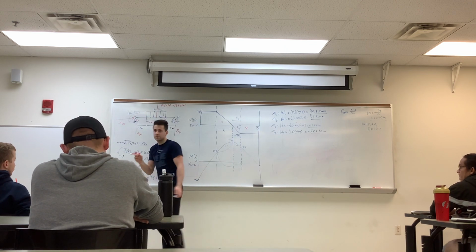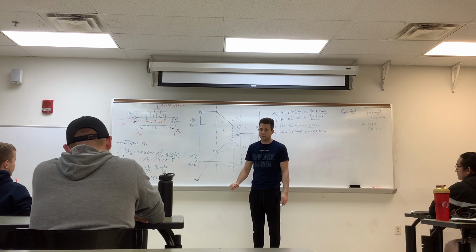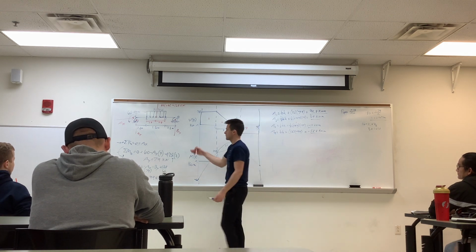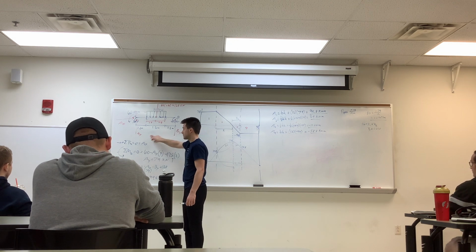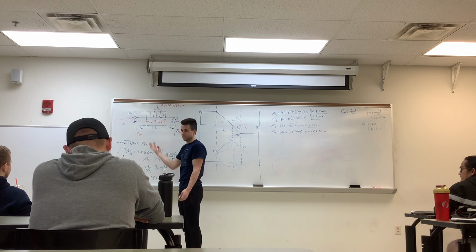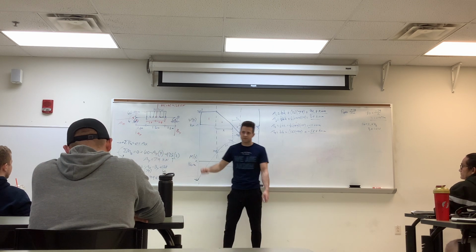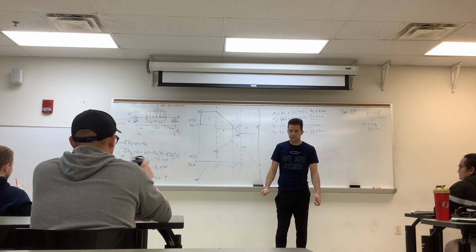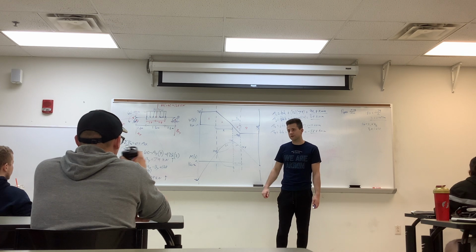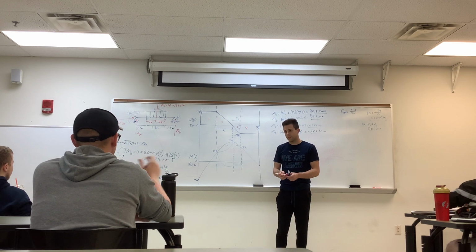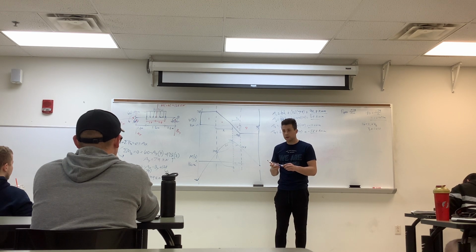Yeah. And the shear, you don't start with anything, right? No, it'll always be 0. So the first step would be always find your reactions. And then that's where your shear diagram will start, the reaction at your support spot. And then from there you'll find everything else accordingly. And the concentrated loading doesn't get put on any of the diagrams. If there's a concentrated load, it acts as a shear at that point. I mean, how we made the 80 into a concentrated load, we don't use that for the diagram.